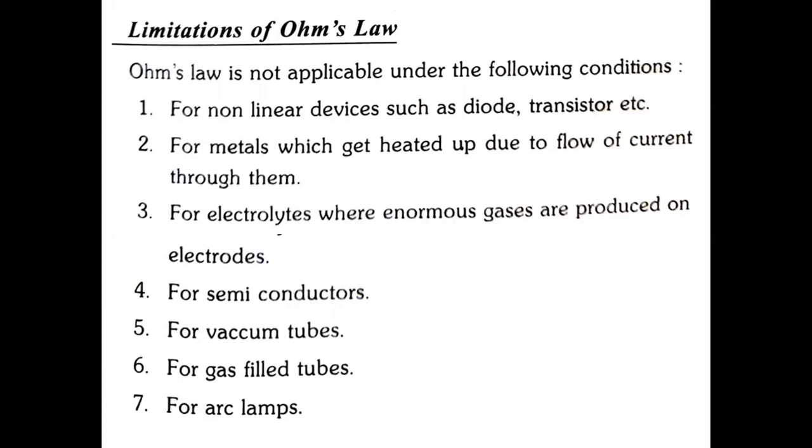Limitations. For nonlinear devices such as diode, transistor, etc., it cannot be applicable. It is applicable to the linear circuits only, linear elements. For metals which get heated up due to the flow of current through them, it is not applicable. For electrolytes, where enormous gases are produced on electrodes, for semiconductors, we cannot apply. For vacuum tubes, for gas-filled tubes, for arc lamps. So these are the limitations of Ohm's law.